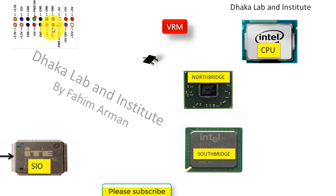I am going to discuss the whole process of the desktop motherboard power sequence in detail. First, when the power supply is connected with the power cable and the motherboard, a voltage enters the IO chip, and this is 5V SB or 5V standby. It will come from this wire.